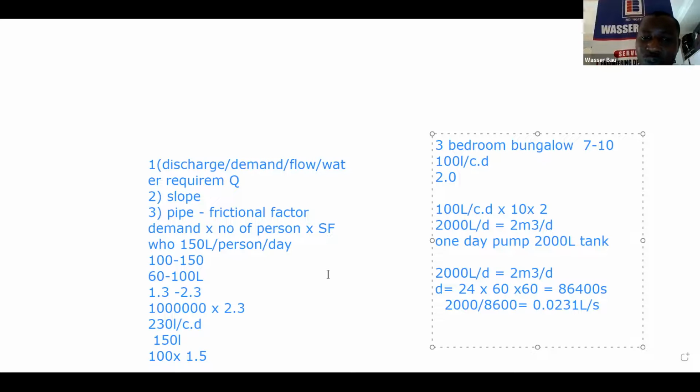But then a range was given to you. So instead of not introducing that safety factor, I would advise you maybe lower it to 1.5, but you have to introduce it because the losses you have introduced are assumptions, made without taking into consideration the new location that is going to be used. Those that came up with 100 liters came up with a generic value. But you will now introduce your own safety factor so that you can take care of the exact uniqueness of where you're designing. Are you getting it? So the second tier safety factor is necessary.